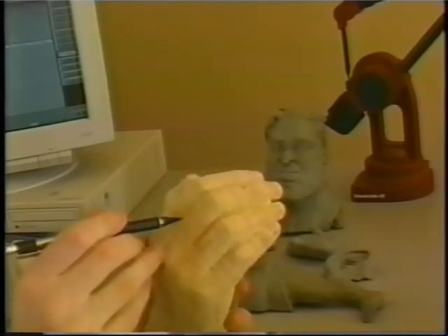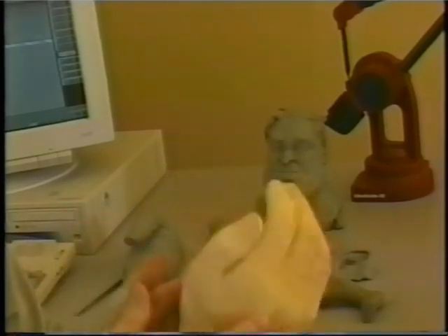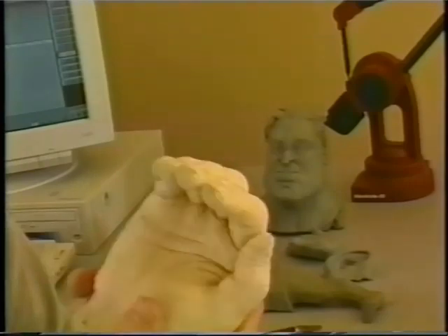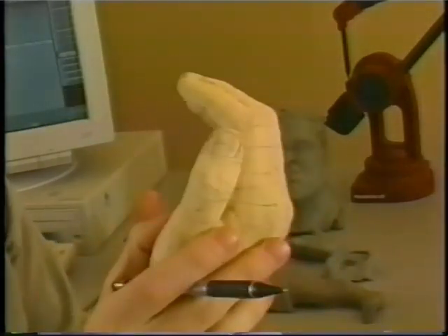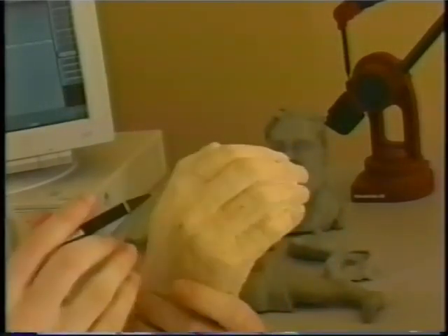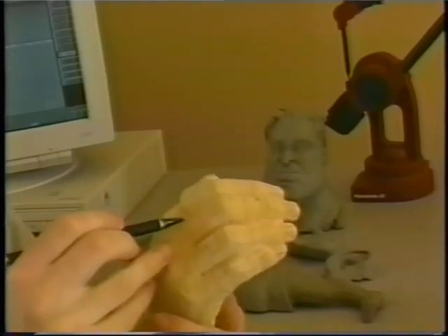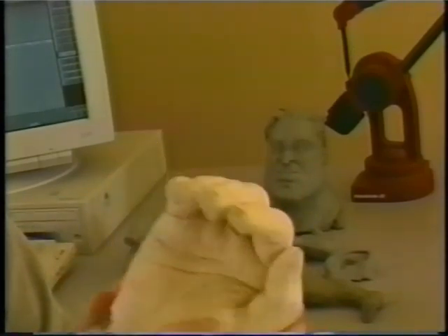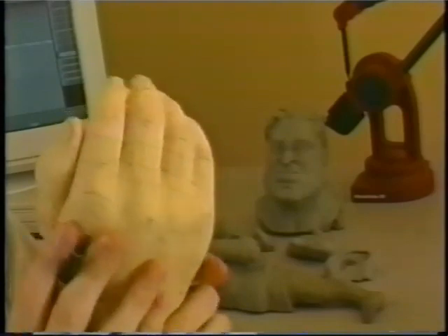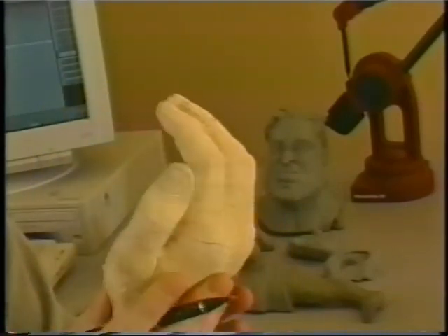The only tricky part is between the fingers. That doesn't look so good. So if you're going to have a view like this, then you're out of luck. Of course, polygons are very good for hands because you simply break into triangles in this area and resolve all that way. But if you're going to use NURBS, this is a very good way to do hands, and it actually works pretty well.